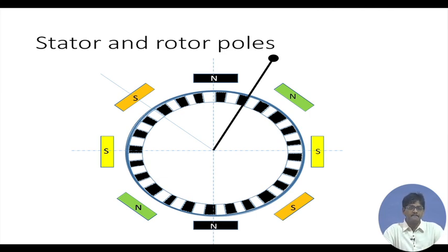Naturally, the most stable direction for the south pole has shifted between the two north poles, and we see that the nearest south pole on the rotor is not exactly aligned with this direction. There is a definite angular phase difference between the present location of the south pole in the vicinity of this particular black line and the orientation of the black line at 22.5 degrees with the vertical.